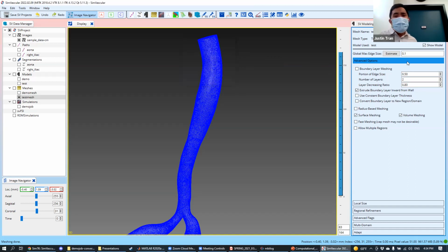factor of 10. So element size is not a linear thing, and it ramps up really quickly. If you have a situation where you have like 6 million elements, maybe you might try doubling the element size. Instead of what you have, maybe you do twice that. Then you're going to end up with a much more reasonable mesh.